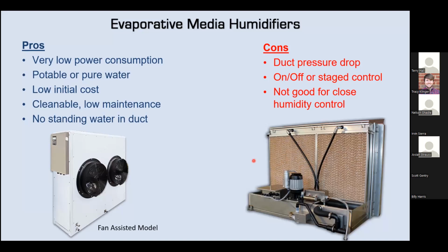fan-assisted model. You're not going to get really close control, because the media is wet and you're waiting for it to dry. You're going to get a bit of a lag on your controllability, so it's not really fit for purpose for a tight control application, but to supply a base amount of humidity for a building space, it works really well. And you're talking about energy usage that's below a kilowatt, just for using the pump, or the energy usage of the fan that you're using to drive the airflow.